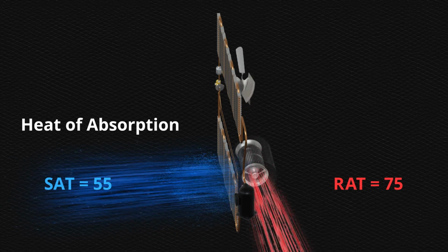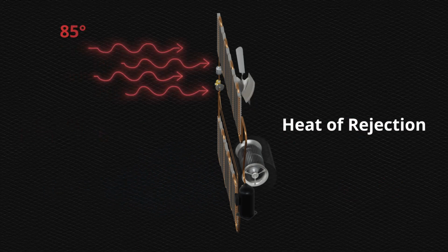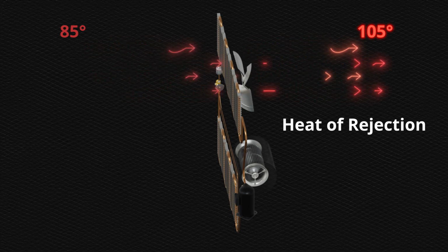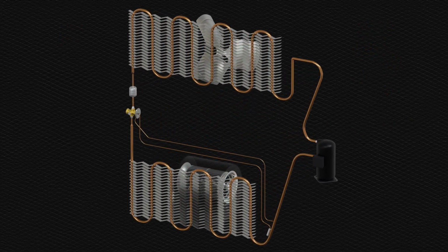In the condenser, the heat transfer is known as heat of rejection. Heat is rejected from the refrigerant and into the outside air because the outside air temperature is lower than the refrigerant temperature. Therefore, the comfort cooling refrigeration cycle absorbs heat from the inside and rejects the heat to the outside.